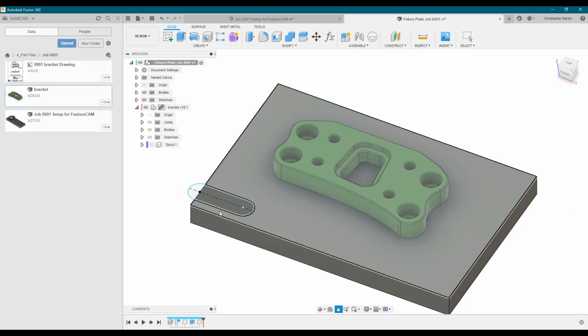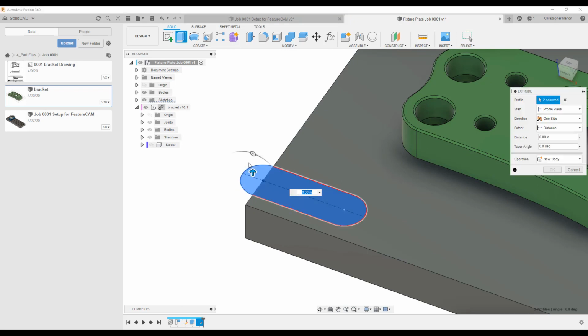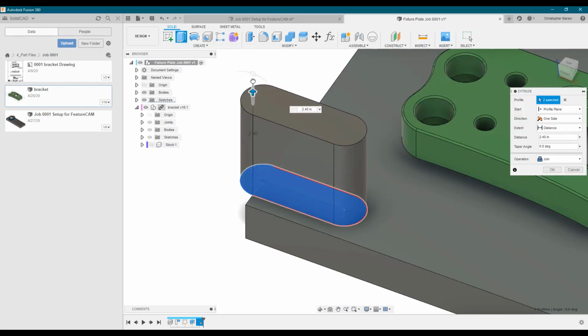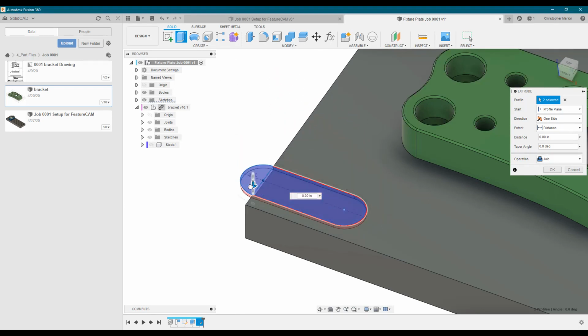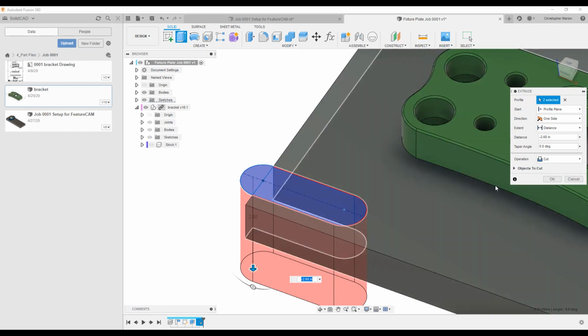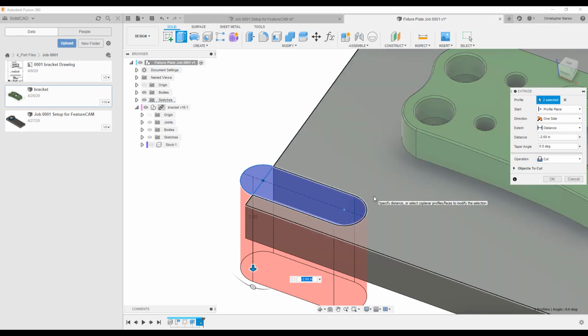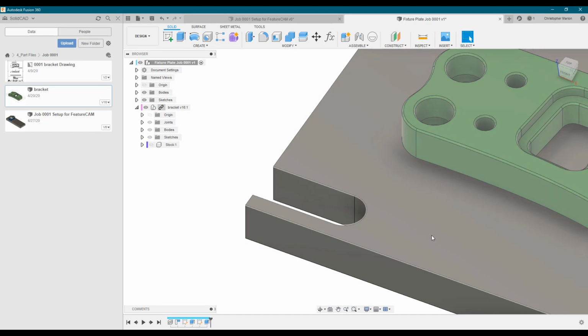So the same thing as before, we're going to use this sketch to extrude through the plate. Right click, extrude. You can also find the extrude function up top. As I extrude up, it always wants to join. If I extrude down, Fusion automatically thinks that we want to cut through our original object, which in this case we will use. Okay, so there's our one slot.